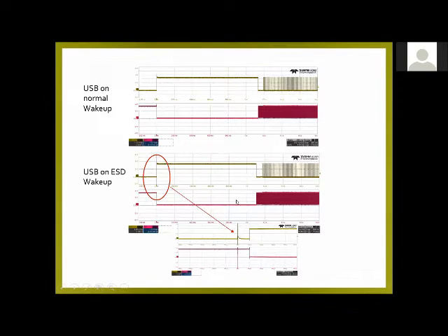And what was happening here was, when we had an ESD event, which you can see at the bottom here, there was a transient on the USB cable. And actually, I should say, I don't think the keyboard makes this signal, the computer makes this signal. So the computer's looking on the USB and sees this transient. If the transient is big enough and long enough, it thinks somebody has hit a key.